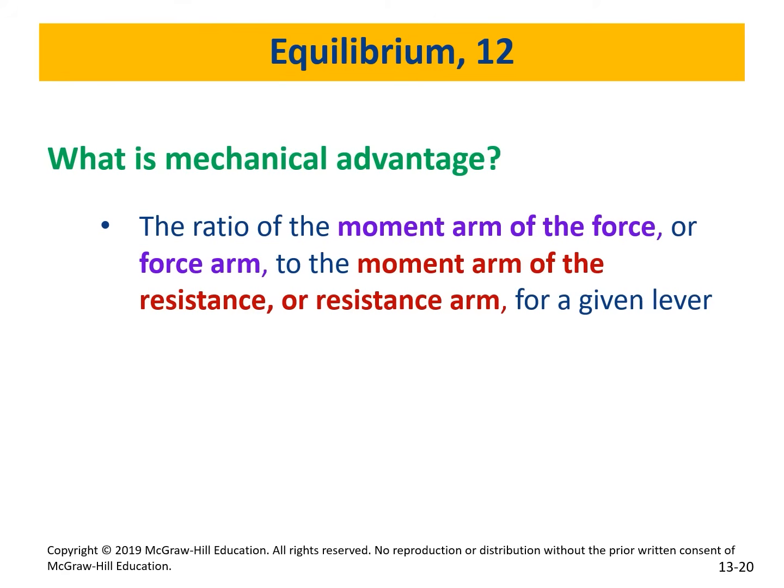So if I have a big rock here, I need to move it, and that's my rod, do I put the small center of rotation here, or do I put it far away? Which one is going to give us more mechanical advantage? The closer, right? Because you are going to leverage that moment arm and multiply it by the force to create larger torque.